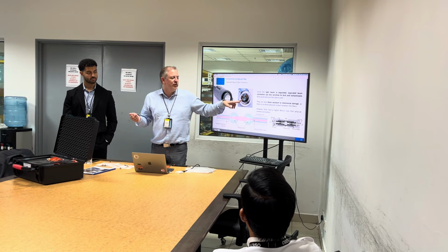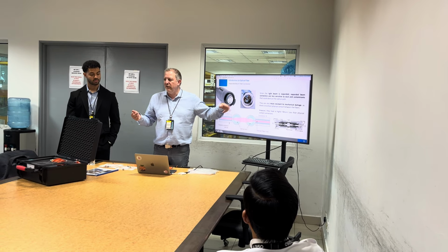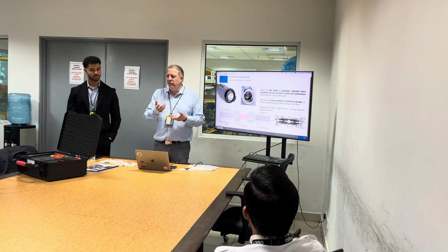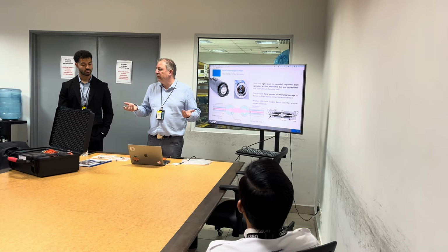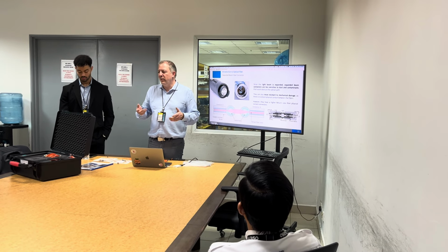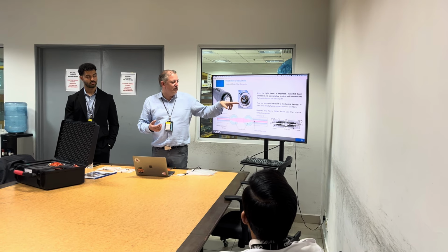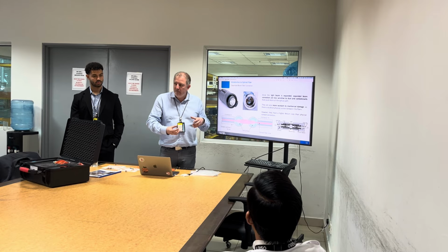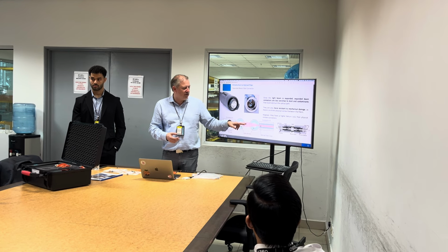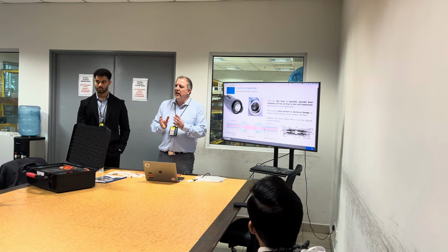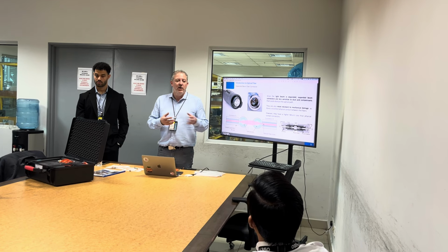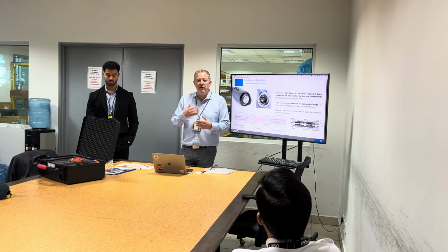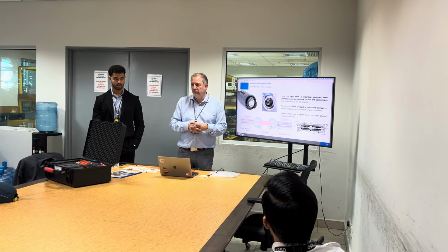So this is mostly used on military systems, where, for example, if you have a recognition pod to plug on a fighter, or if you have a laser designation pod, or any weapon system where you need high rate transmission with fiber optics, they use this because each time they install the system on the aircraft, they're gonna plug, unplug, plug, unplug. So they want something which is less sensitive to any misalignment or any dust or any pollution, so they don't have to worry much about cleaning of the connectors.